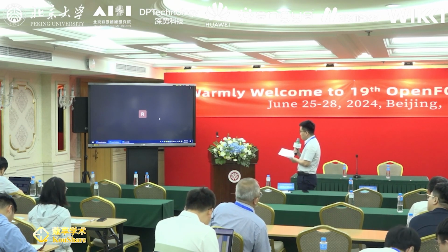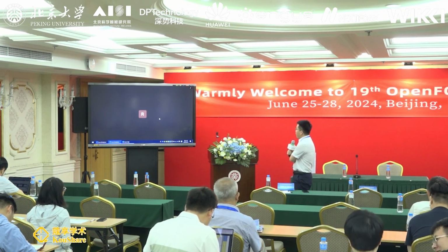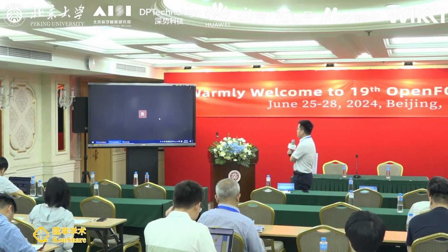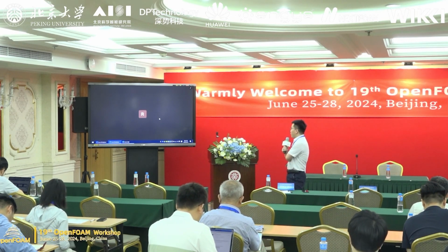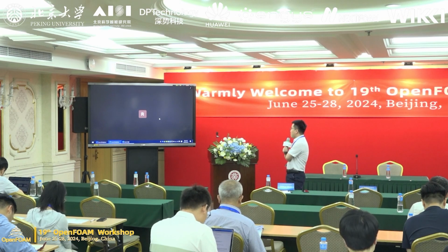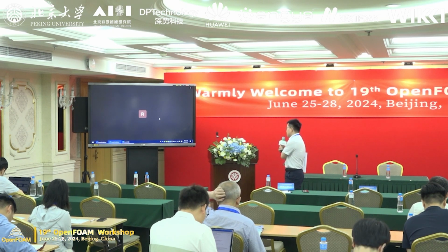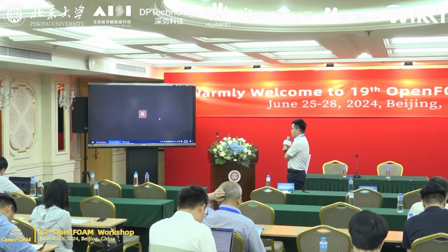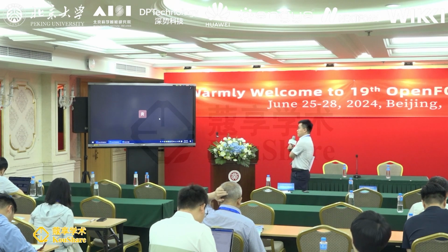That's a very, very good question. I can answer this if we look at the general model of ZDDP growth and anti-wear behavior. There are experimental results where people can measure the thickness of the films evolving throughout time. In this case, these things are very small. They are of nanometer scale, micrometer scale. They are in contact. It's just simply hard to measure.